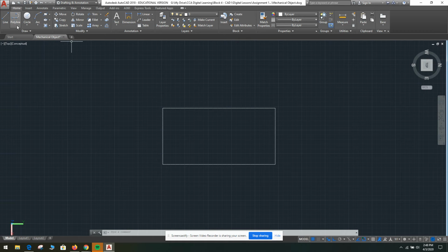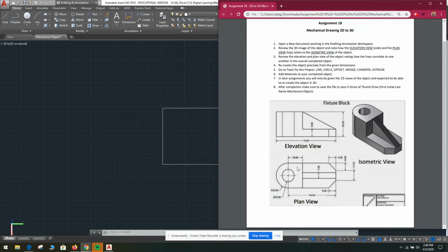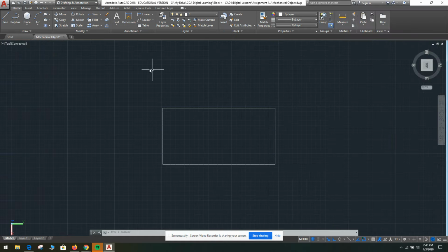So if you look at your diagram here, you have a 15 diameter circle and then a 30 diameter circle here. Okay, so to recreate that, you can do it one of two ways. You can come in with this circle, and on the midpoint of this back line, recreate your 15 circle, and that 15 circle is 15 divided by 2 because what they're giving you is diameter.